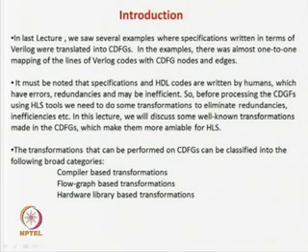Then we emphasize that Verilog codes are converted into CDFGs. So, that is an automated flow, but the Verilog codes are developed from the human specification. So, the way you are writing your Verilog code will decide the outcome, because that is the input to all the CAD tool algorithms or the formal algorithms. The input is the Verilog code.